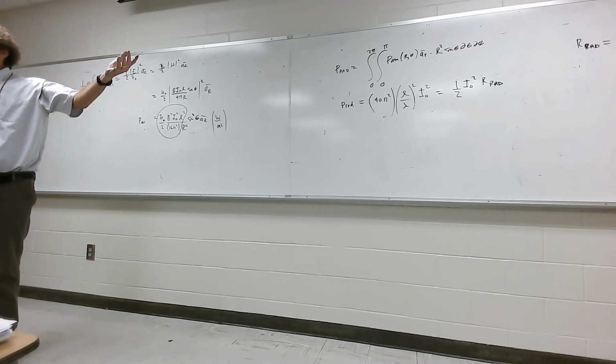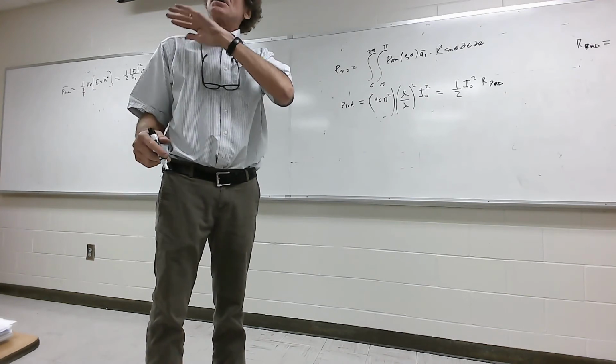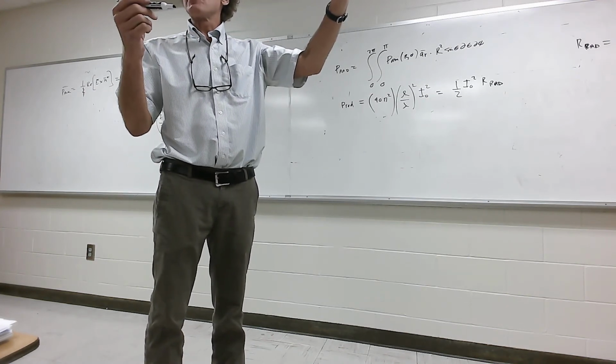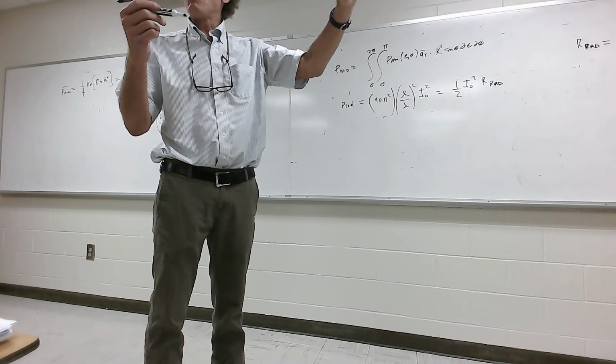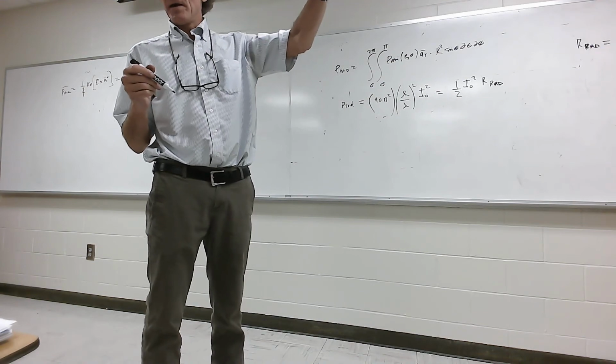That's not much. You would like to have an input impedance much higher, because that way a smaller current would radiate the same amount of power. And the more current, the more ohmic losses you have. Remember that. You're always trying to minimize the current needed to generate the power radiated.